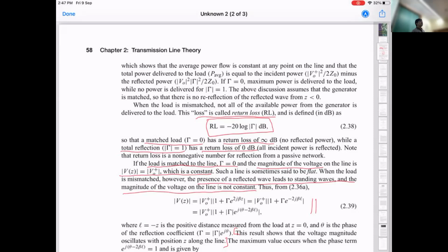So one example of a figure of merit which is often used is a return loss of 20 dB. You say that if your return loss is 20 dB or more, it is usually considered a good match. Now let's qualify this good. What does it actually mean? So 20 dB here would mean that your reflected power is 1%. If I come out of the log units, it's 1%, because it's 10 to the power 2, and 1 over that is the amount of reflection you're getting.